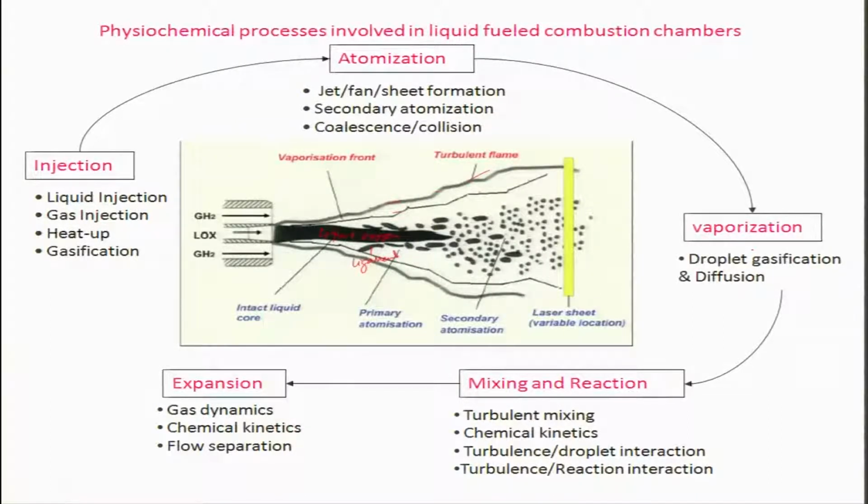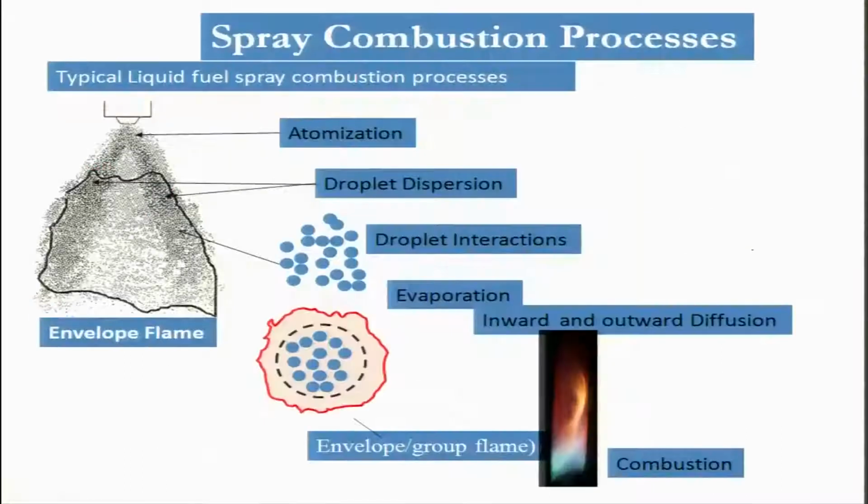So, I have just given you the bird's eye view of liquid fuel combustion. Unlike gaseous fuel combustion, liquid fuel combustion is quite involved to understand and to model, right. And it is a two-phase flow. So, turbulent flow, heat transfer, mass transfer, chemical kinetics, quite complex, and also the droplet size distribution will be changing, and all are random in nature. Keep in mind the atomization process is random in nature. So, I will just give you some idea about that.